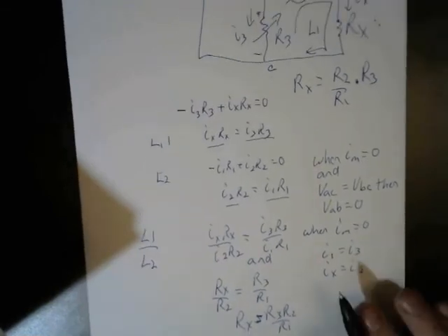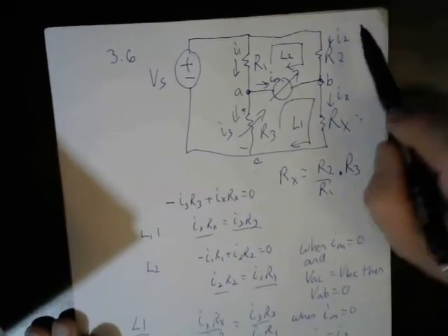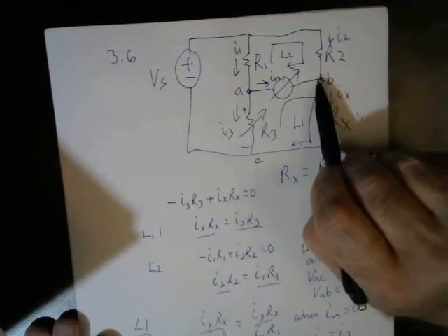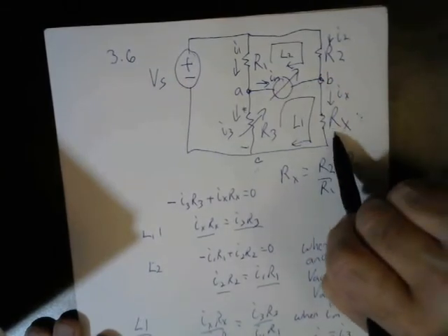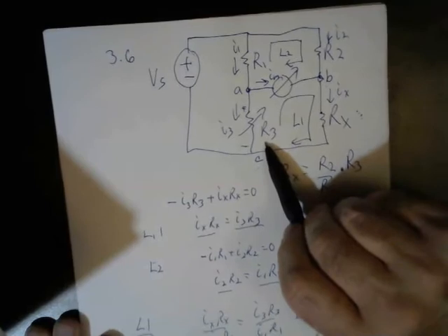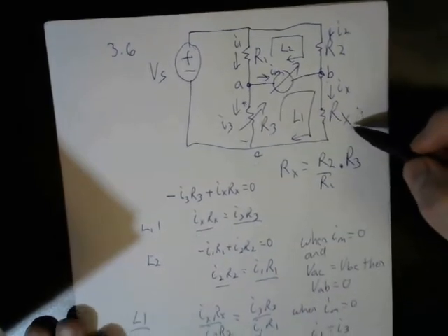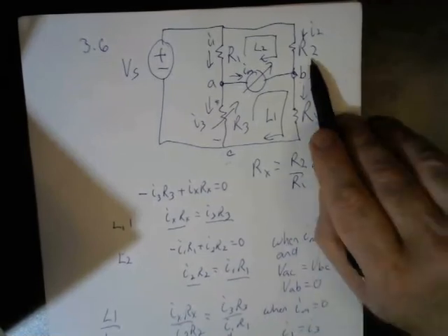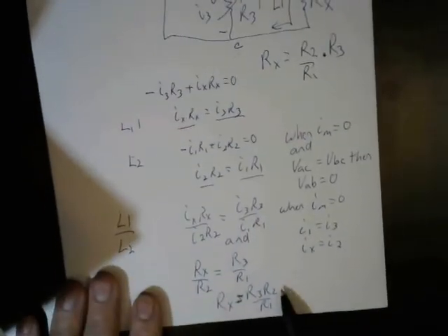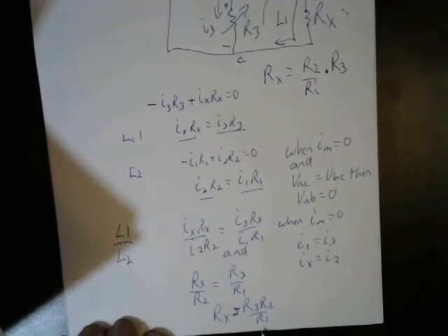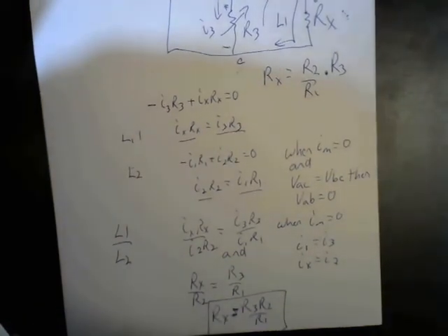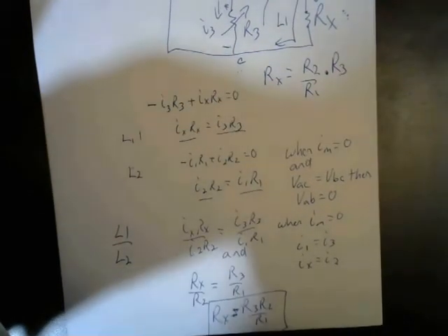The neat thing about Wheatstone bridges is you could use a crude voltmeter or a crude ammeter, and it could have a very low resistance, and you can still get very accurate measurements of Rx by just adjusting R3. And also, let's say that Rx is a very, very high resistance. You can use a very high resistance in R2 and then have R1 and R3 in completely different ratios, and it'll still work. So this is the relationship you're looking for, and that's how a Wheatstone bridge works, and we're just proving it.